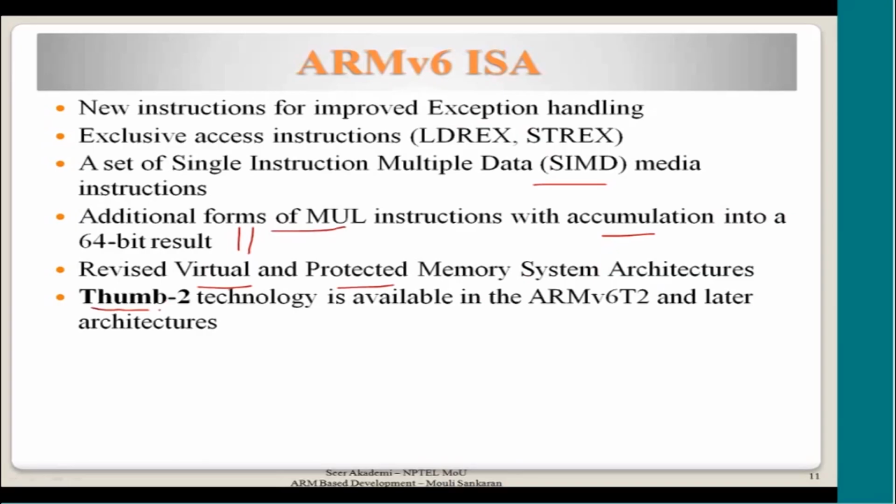And then, we saw ARM and Thumb state, but Thumb-2 technology is a little improvement on that from V6T2 versions. So what exactly this does is you can have both Thumb state 16-bit instructions as well as a few 32-bit instructions too, in the Thumb state. So what happens is here the format is different.